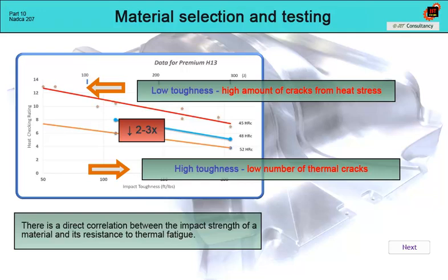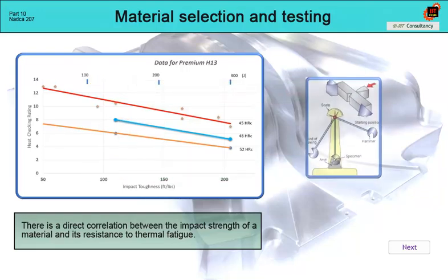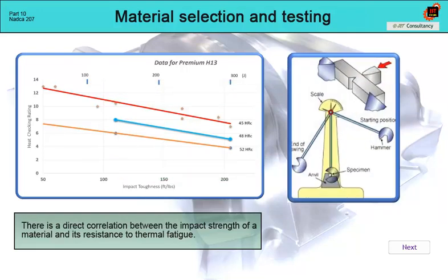The first question is, why impact strength, when there are a number of other analytical tools to detect structural defects in a material? However, the impact test is unique in that it provides cross-sectional properties of the material, which, though they average the effect of possible material defects, are sufficiently sensitive to these structural defects. At the same time, from the point of view of costs, it is a test where we get the result at an acceptable price and in a reasonable time.